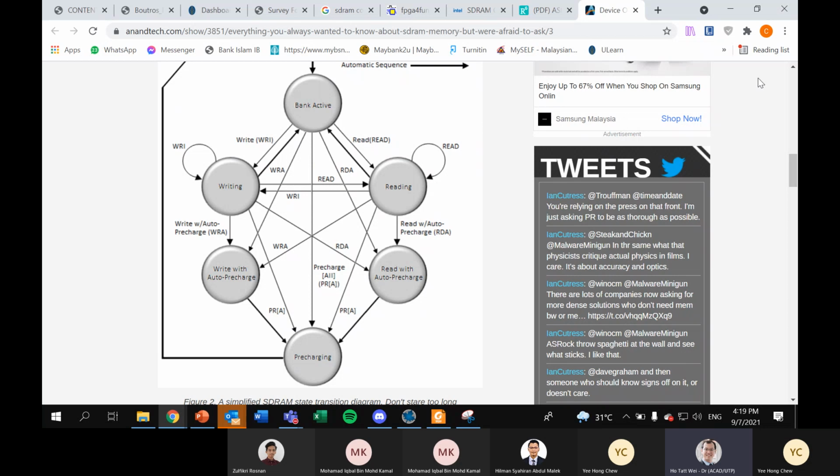Okay, understand. So, basically for each operation, whether it's write or read, the thing we need to consider is the commands themselves. There's usually a three-step command. If you're doing a read, you need to do a row access strobe, a column access strobe, then clock out all the values in sequence, and then do a precharge. If you're doing a write, it's directly the column access strobe. You send in all the values, and then you do a precharge.